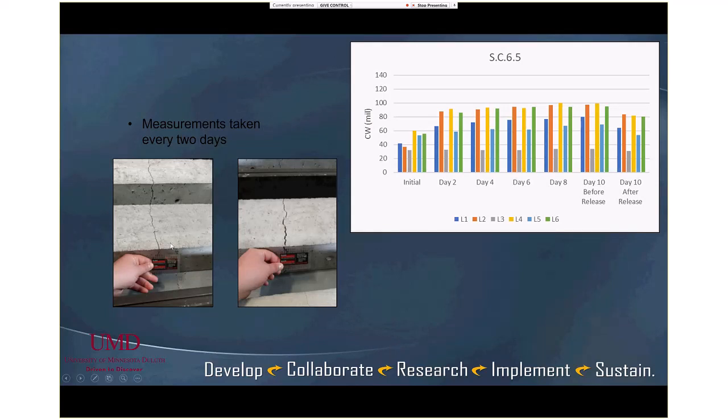You see, if you just keep the beam in tension and then slowly the fiber gives up, maybe the fiber is pulling out of the concrete or it gets some plastic elongation. So we could see some creep occurs, and we believe that the same thing can happen in the field, but this can change using different types of fibers.